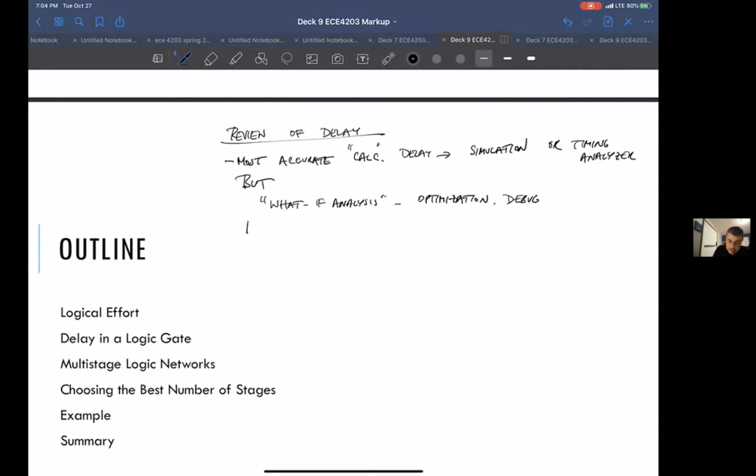So that's why we're looking at doing a hand estimation or Excel sheet estimation tool. And that's based on, like we said, it was roughly accurate, depending on a lot of dependencies, but it's in the sort of 10 to 15% range, but good enough that it can tell you roughly where you are, how many stages of logic you most likely can have in each process between flip-flops and those kind of things.